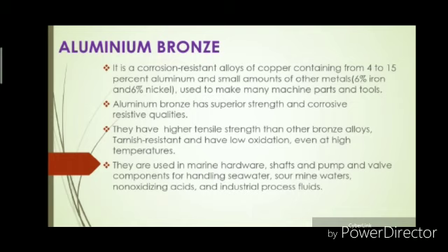Because of its low oxidation property even at high temperature, it does not get corroded easily. It does not get reacted. So because of its high strength and corrosion resistant property, these are used in marine hardware, shaft, pump and valve, component for handling seawater, sour mine waters, and non-oxidizing acids and industrial process fluid.